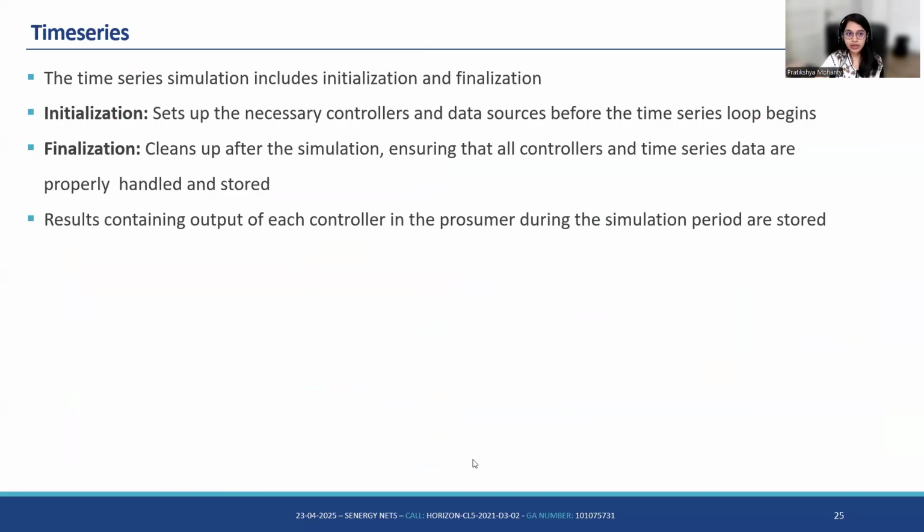And finally, we have the functionality of time series, which also follows from pandapower. So we initialize the necessary controllers and data sources before the time series loop starts. And after the power flow has converged, we finalize everything and ensure that all the results are handled properly and are transferred to the next controller after the simulation period ends.